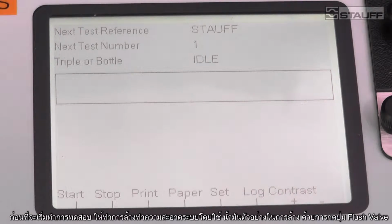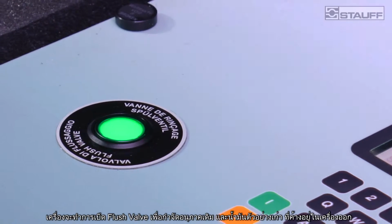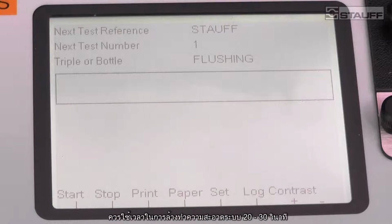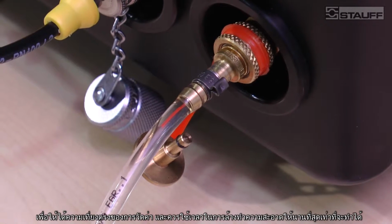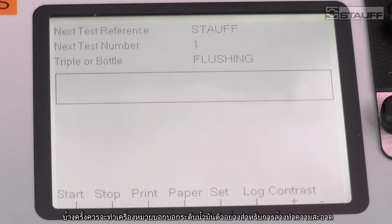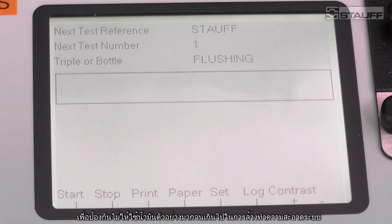Before you press start, ensure that you flush the particle counter to remove any old oil or any air that's been entrapped in the system. Make sure you flush for at least 20-30 seconds because you want to give that particle counter a very good flush and not influence it by any other oil that was left from the previous test. So the particle counter shows flushing mode. Sometimes it's a good idea to mark the bottle for the level that you want to flush, so to make sure that you don't run out of the oil sample.